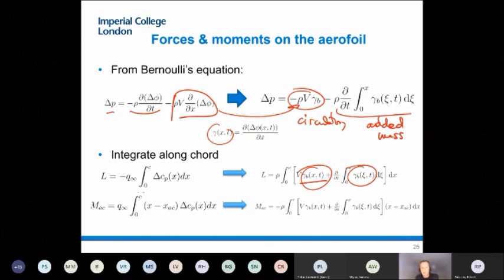We discretize that distribution of circulation on the wing and the wake. We integrate all these pressure forces. We compute the propagation of circulation as you run down the wake, and that can be numerically written with not too much complexity. And then we obtain those time domain evolutions of aerodynamic forces.